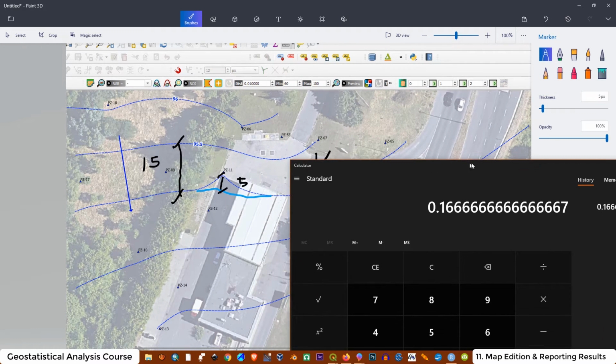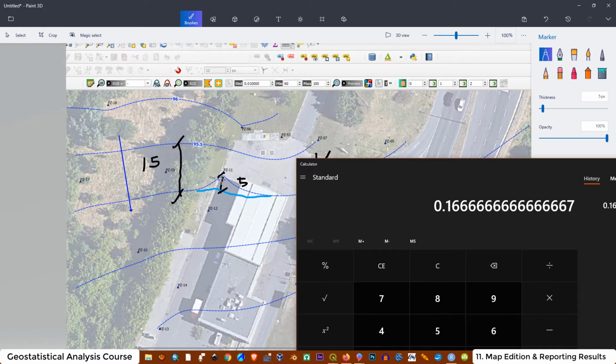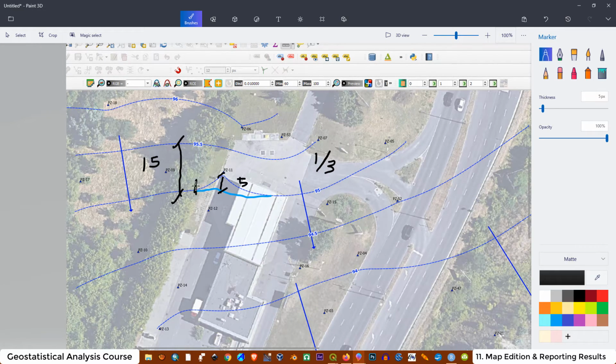That means that this contour line over here with this shape is elevated 0.16 meters from here to here, and from here to here is 0.5 meters, as we saw here, the difference of the contour lines. But from here to here, the groundwater is elevating 0.16 meters. That means it is 16 centimeters. Then also we can measure the distance from here to here. Let's see what happened.